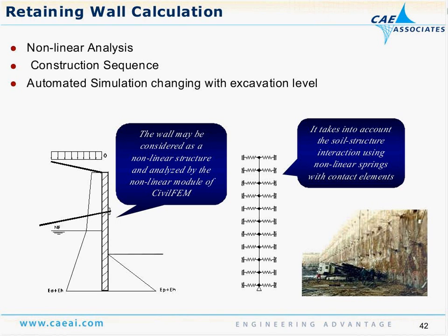It can do the nonlinear force deflection response and calculate the appropriate loads, stresses, forces in the members, in the wall itself, in individual beams. You can pretty much integrate any ANSYS feature into any of these different processes.